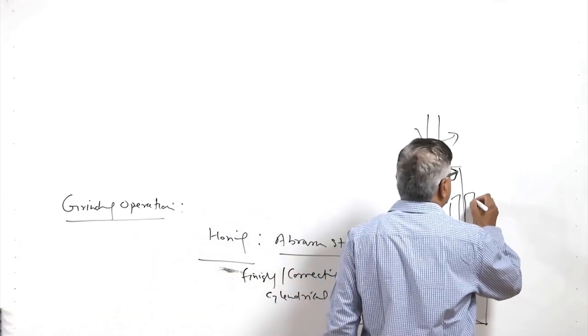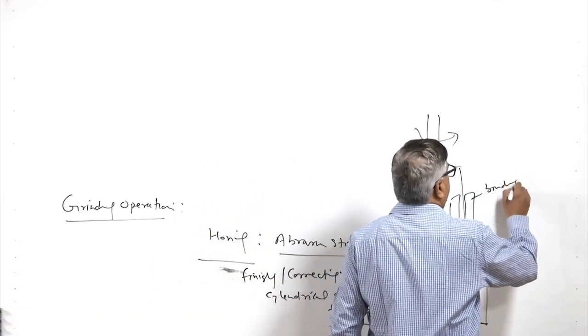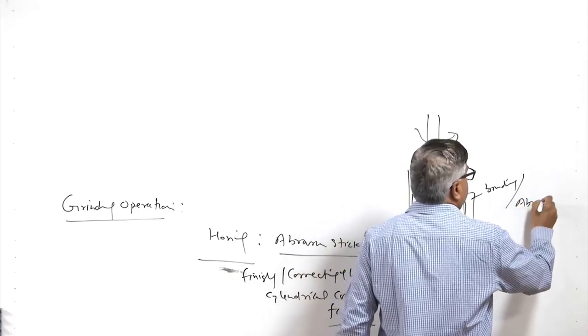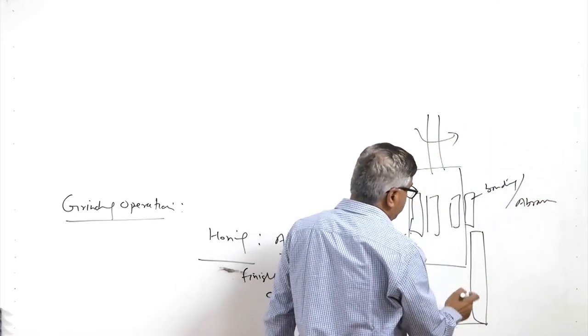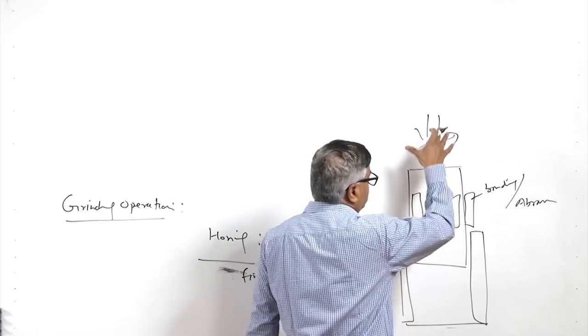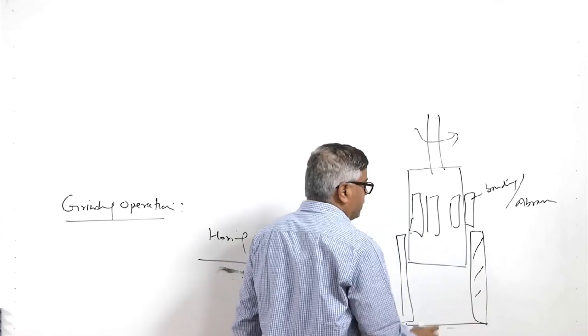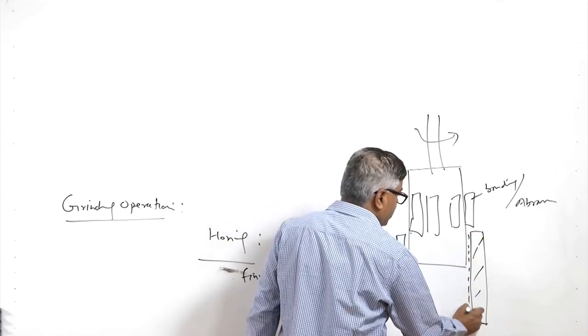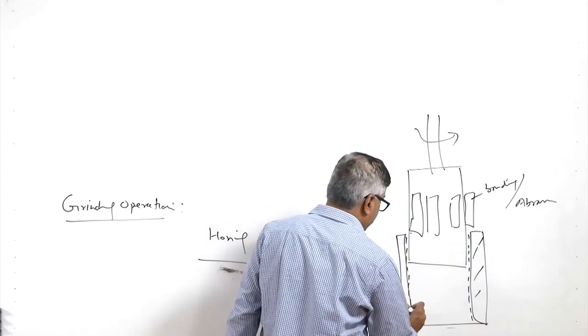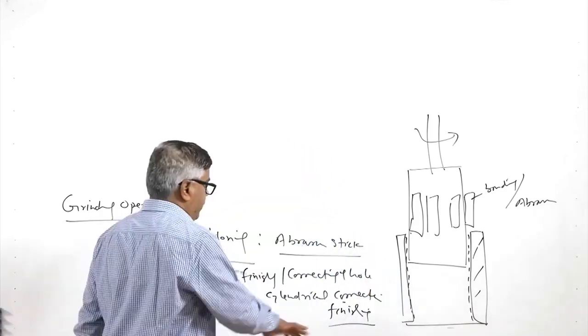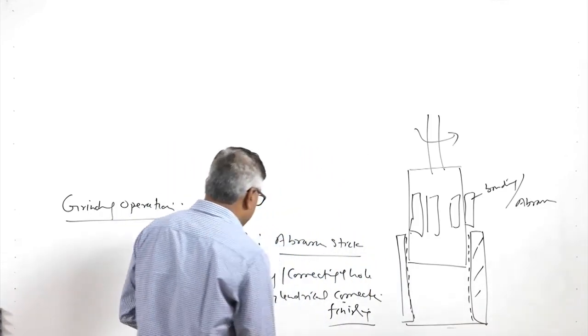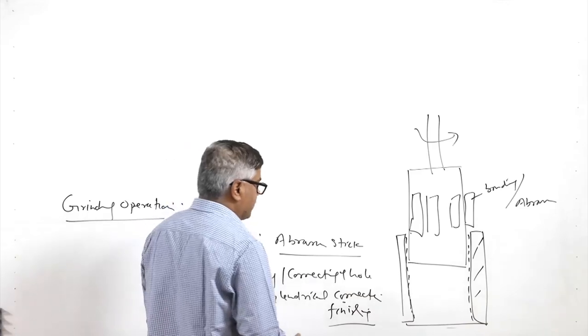These abrasive sticks are made of a bonding material and abrasives. So, when the rotating tool interacts with the internal surface of the workpiece, material is removed from the internal surface in order to correct the hole dimensions as well as to give the desired surface finish.